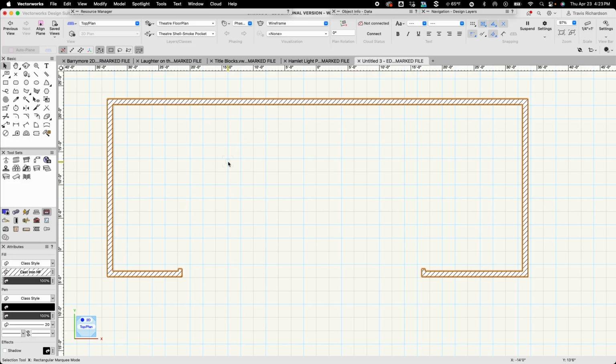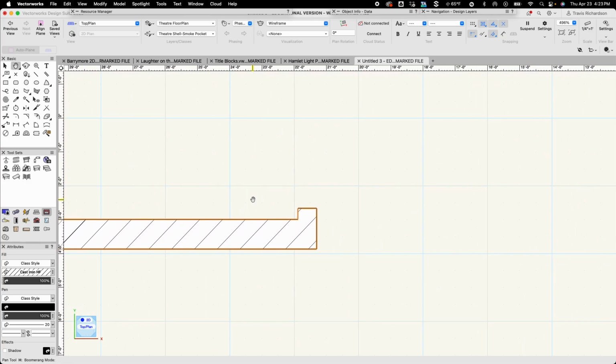So I'm going to start my double line polygon tool again, and this time I'm going to be in right control line mode, and I want to change my separation to be 1/4 of an inch. And I'm going to zoom in on this downstage right section, and I'm going to go right to this endpoint and start my polygon.